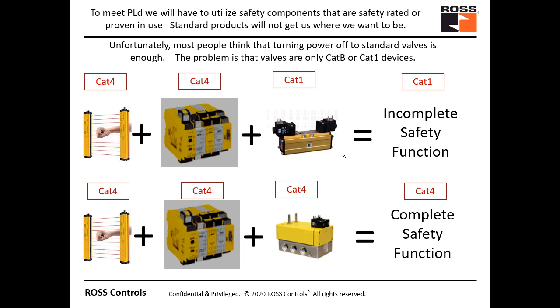And I'll show you this when we get to the ISO 13849 portion. It is made up of category plus something called reliability, another piece called diagnostic coverage, and a fourth piece called CCF, or common cause failures. So if we start with a good quality product that is at a high level like these are, it gives us a better opportunity to meet the performance level requirements down the road, and I'll show you that now.